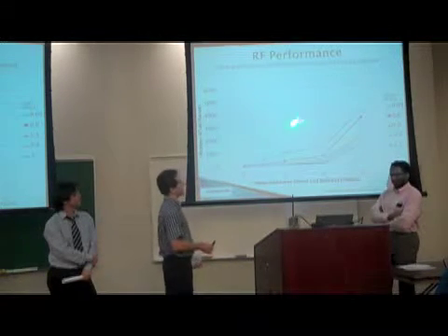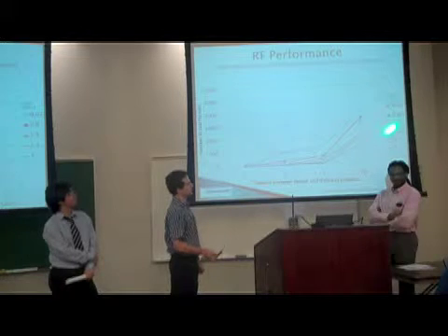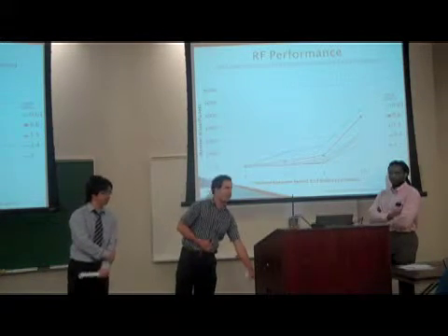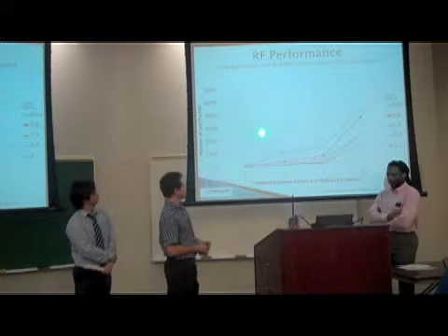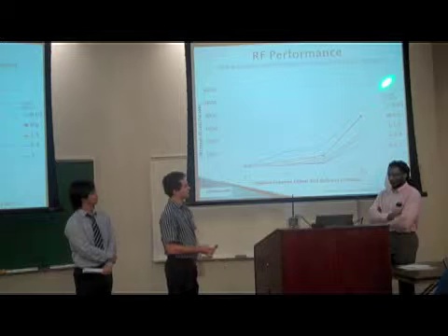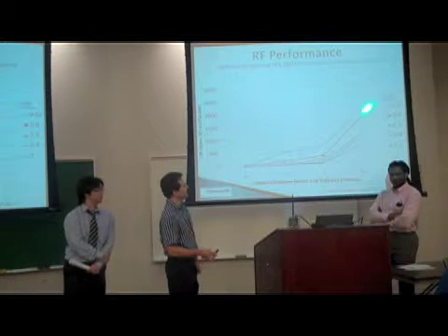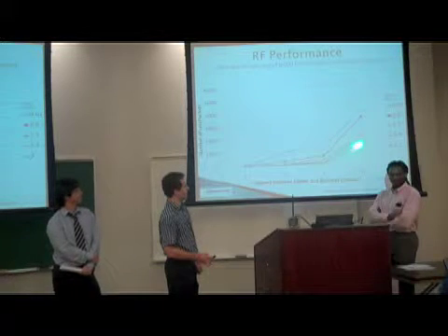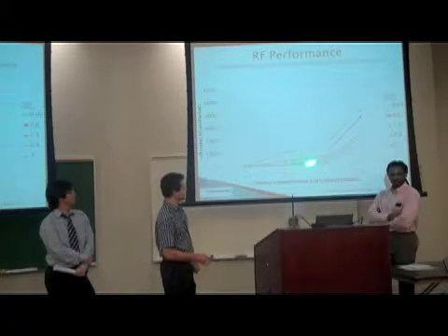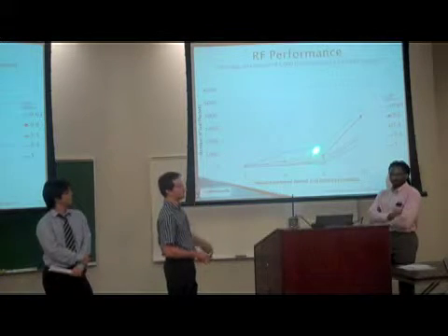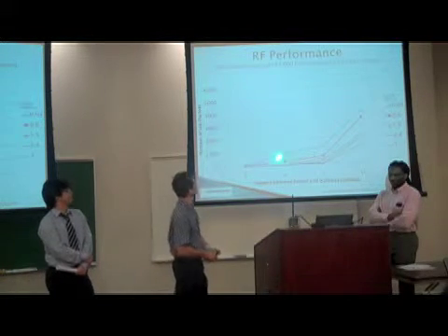We tested at various heights for the gateway placement. The sensors, of course, are on the surface of the Earth. What we discovered was that having the gateway also located very close to the surface of the Earth, we encountered a lot of dropout. So by raising that gateway up, we can get a further distance, and this gives us a good idea of how far and how high we should place that gateway for optimal communication.